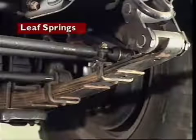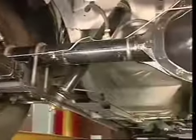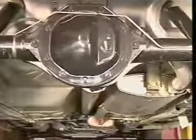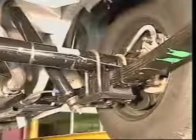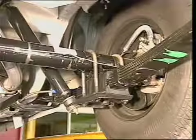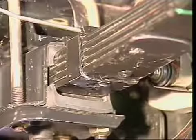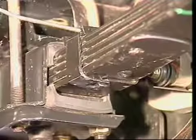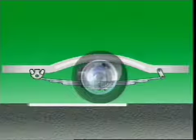This section examines leaf springs. The leaf spring is one of the oldest forms of springing. It is usually used on rear-wheel drive vehicles because of its simplicity. They are normally mounted longitudinally. Leaf springs consist of one or more flat springs made of tempered steel. A number of leaves of different length are used to form a multi-leaf spring.